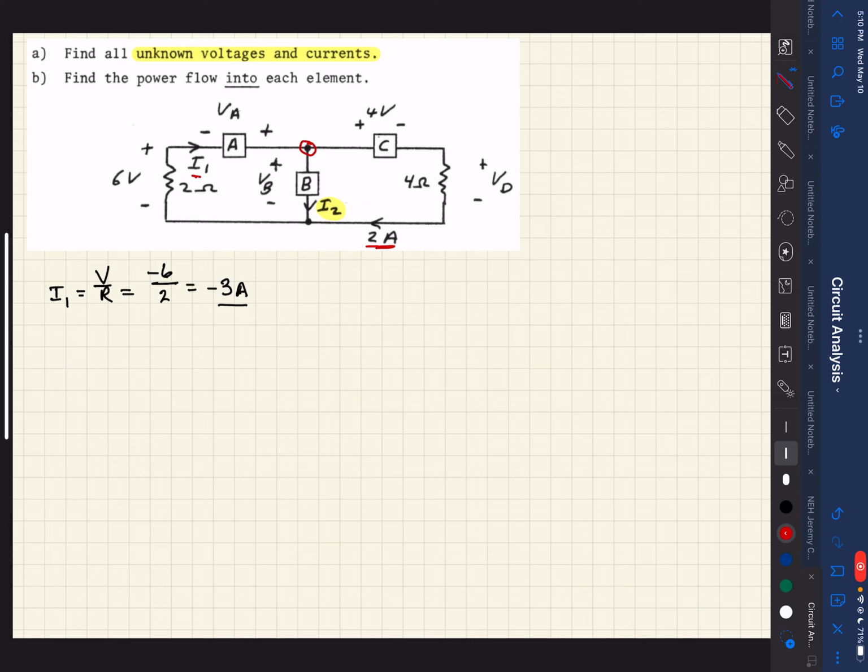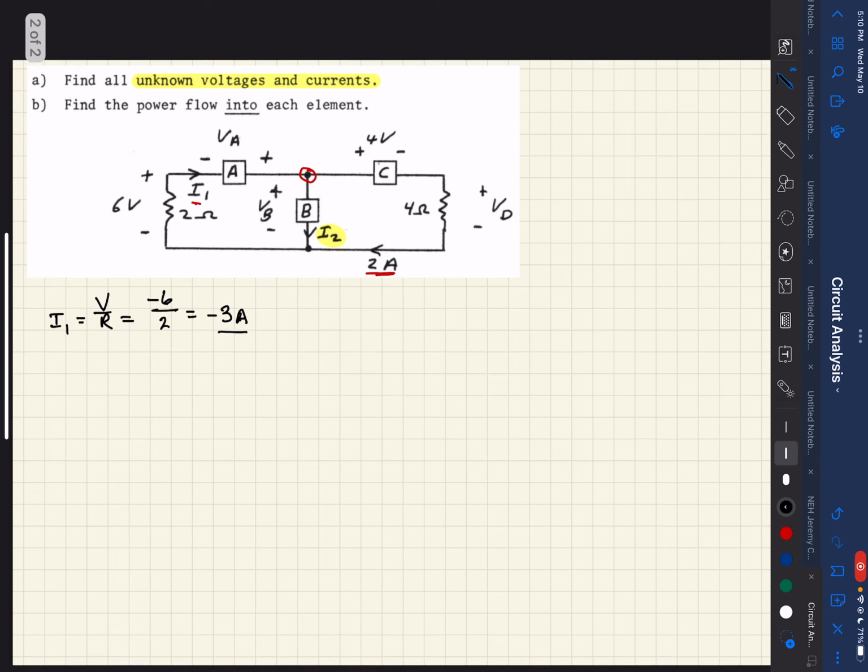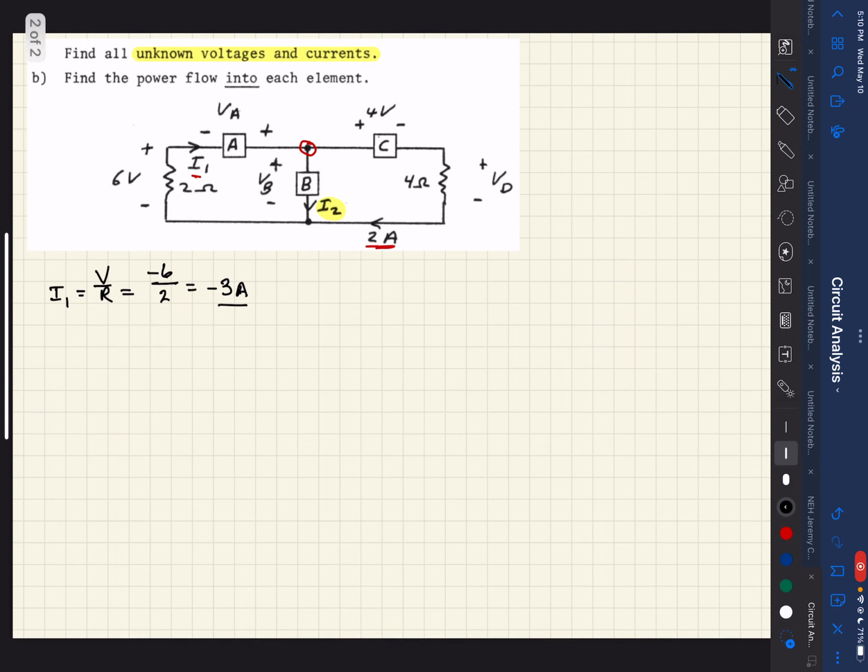That being the case, we should be able to apply Kirchhoff's node analysis and determine what the currents are. If we sum up all the currents leaving or entering that node, it should equal 0. So we're going to arbitrarily pick a direction that says all the currents leaving the node should equal 0.